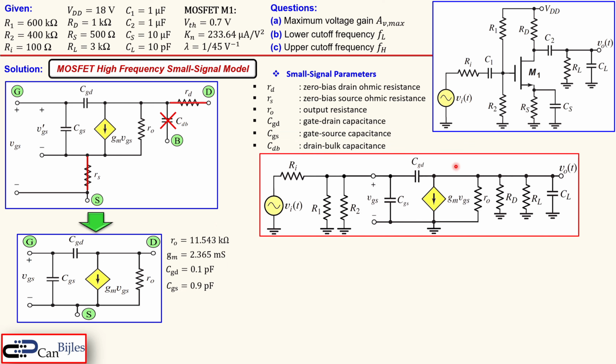So you see here the actual model in the middle, and the R1 and R2 and RI, and also the RD, RL, etc. In this case, one thing is important: C1, C2, and the CS are all also shorted, so that's also what we have. CL it's not, because that will determine definitely the upper cutoff frequency. So that's why you see it in the picture.